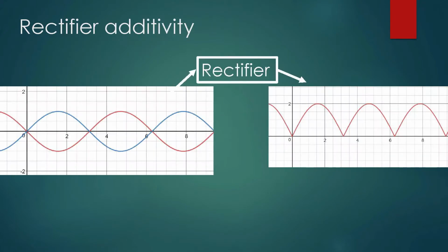For another example, let's say that we have 2 sinusoidal waves that have equal magnitude but are shifted by a period of 90 from each other. To pass additivity, the output should be 0, since the positive of one wave should cancel with the negative of the other wave. The rectifier, however, would produce a positive signal with a magnitude twice as big, because it absolute values the signals and then they would be added together and doubled.